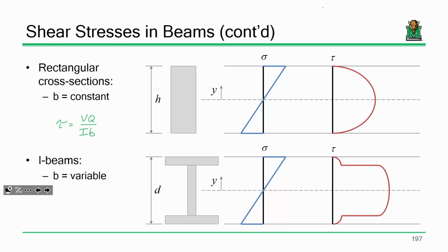Largely when we design I-beams, let's say a plate girder in a bridge, we tend to split them up into their separate components. And we design the web to resist all the shear, and we design the flanges to resist all the moment. That's an ultra simplified way of saying it, but pretty close, right? That make sense? Any questions?